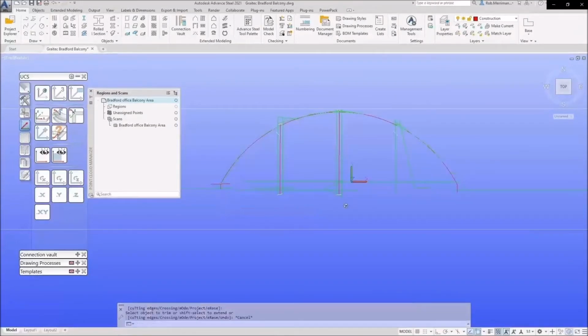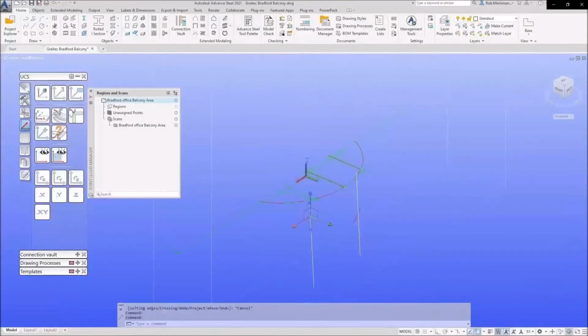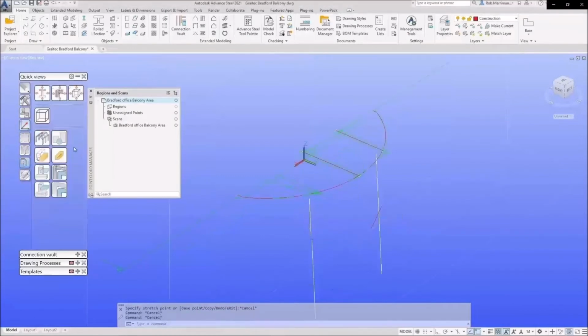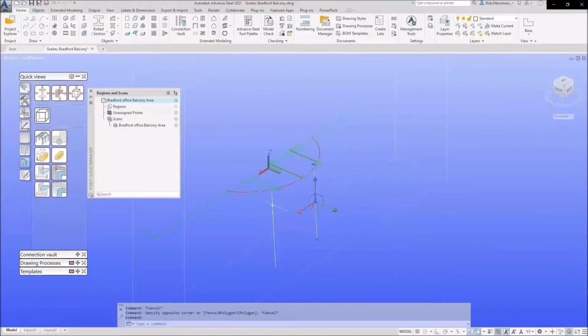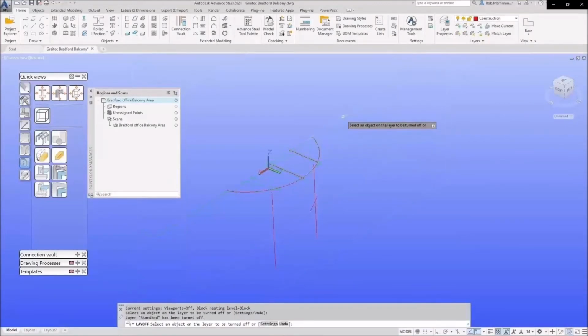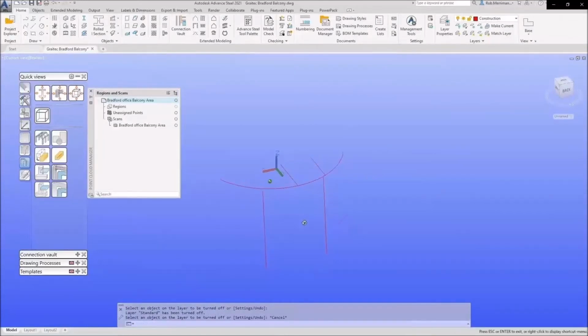Forgotten to trim that last little line. You can see now we're actually getting the center lines of the steels. Now the center line that the AutoCAD command extracted from the point cloud, it did it in 2 parts. So we'll just make that left one there just one line. And again, we can then put those on the construction layer. So we now have the beginning points of our steel balcony. I've obviously still got one more beam to do, but I think everyone gets the idea.